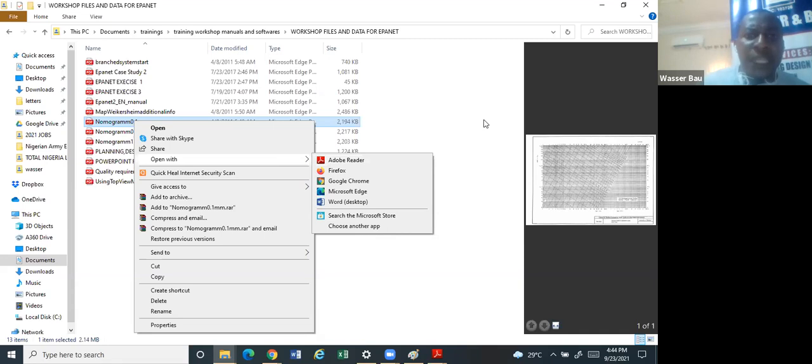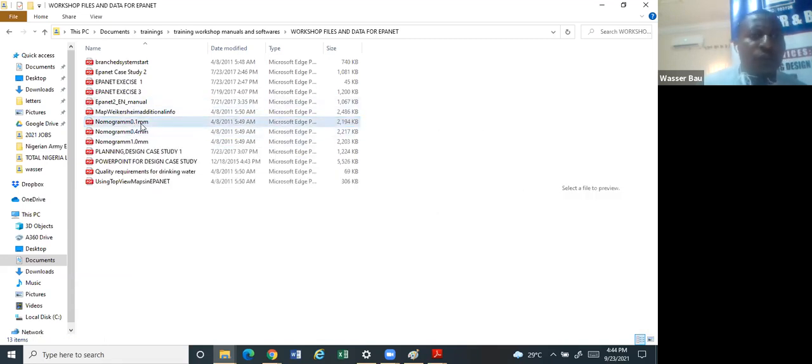So in this material that we are giving you, we have included 3 different charts, depending on the roughness factor. As I said again, there are 3 factors you need to size your pipe: the flow, the slope, and then the pipe roughness or the frictional factor.